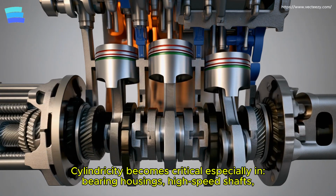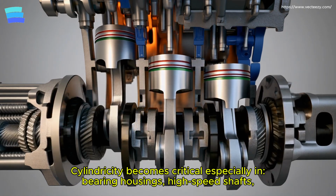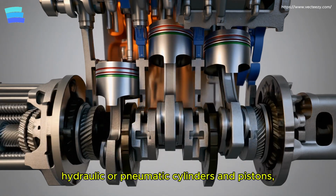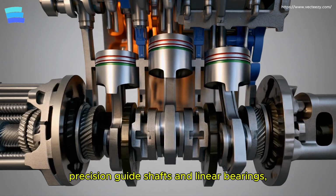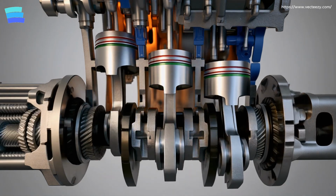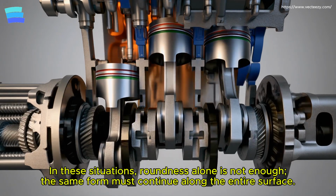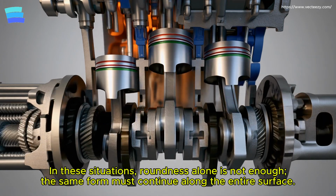Cylindricity becomes critical especially in the following cases: bearing housings and bearing seating surfaces, high-speed rotating shafts, hydraulic/pneumatic cylinders and piston surfaces, precision guide shafts and linear bearings, parts joined by press fit, interference fit. In these situations, it is not enough for the individual sections to be round. The same form and the same diameter behavior must be maintained along the entire surface.